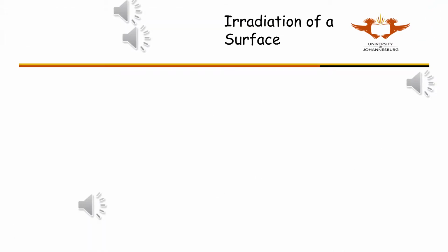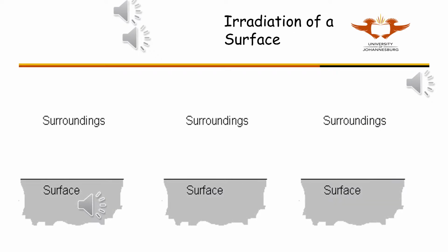Radiation from the surroundings will arrive at a surface as G, the amount of watts per square meter. In order to obtain the radiation absorbing rate for an ideal black surface, which would absorb all the irradiation, you have to multiply G with the area, A, of the surface. For other, non-black, surfaces, you have to multiply the irradiation by the absorptivity, alpha, to get the rate of radiation energy absorbed.